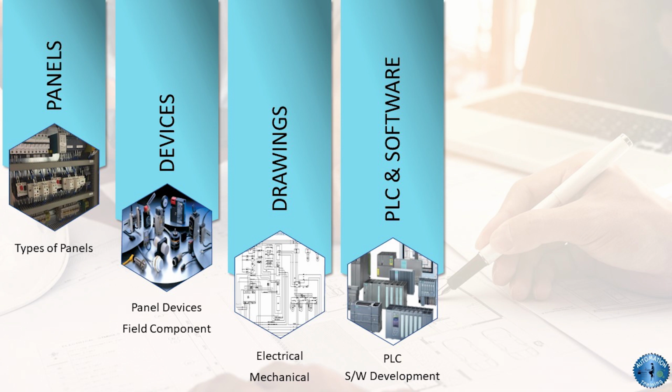Relays have to be hardwired to perform a specific function. When the system requirements change, the relay wiring has to be modified. In extreme cases, such as in the auto industry, complete control panels had to be replaced since it was not economically feasible to rewire the devices with each model changeover. The programmable controller has eliminated much of the hard wiring associated with conventional relay control circuits. It is small and inexpensive compared to equivalent relay-based process control systems.